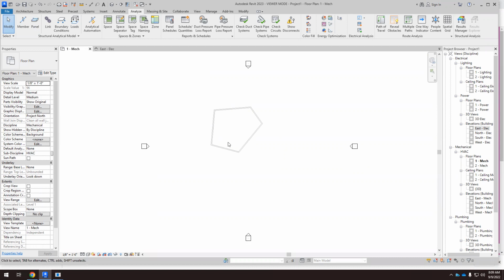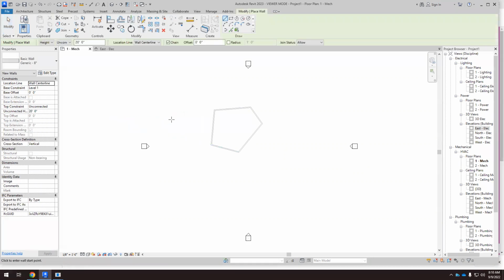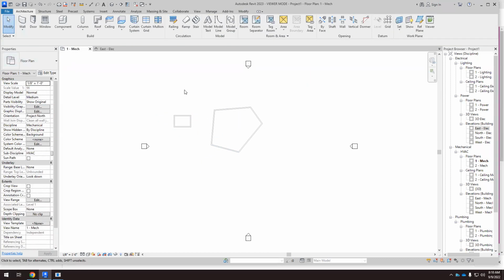So are you all on the same page? Okay, so we create a wall, but we can select it. So here we have a template. So at the beginning, we can define what template we are working with. In this case, we have selected systems, and that's interesting because we can model things. But once we have done this, we can select the walls. This is because this template is there to design systems. Usually we create a building using the architectural or the construction template, and then we open the mechanical template to design the systems.